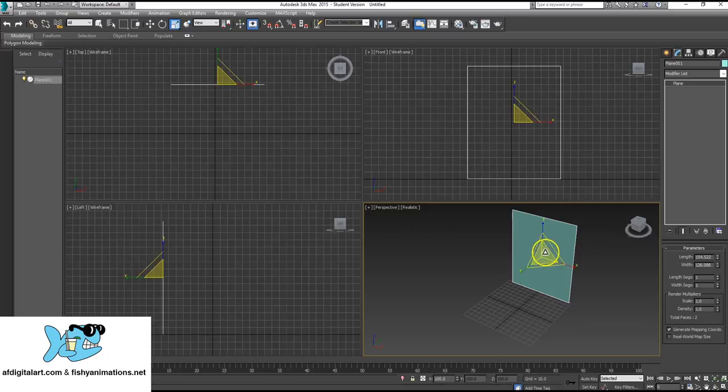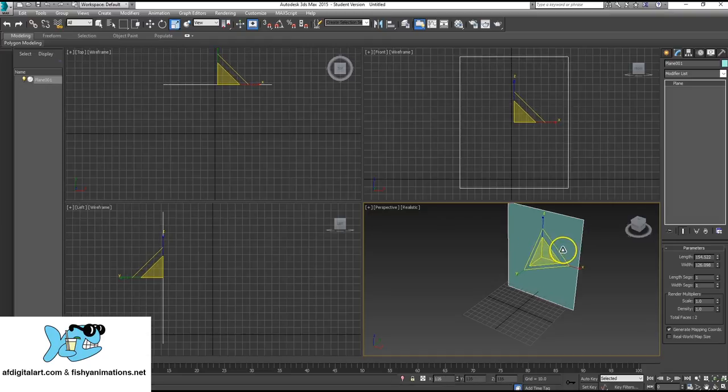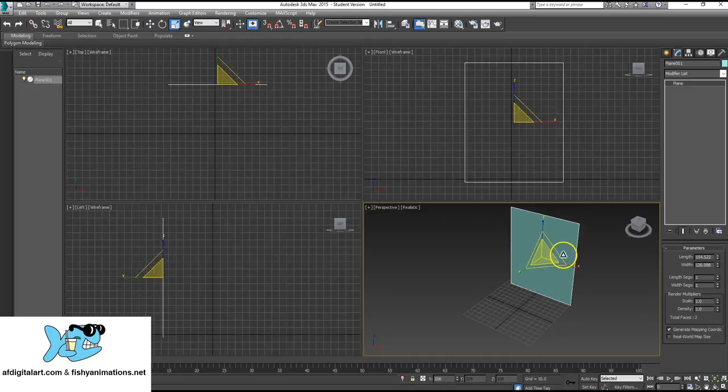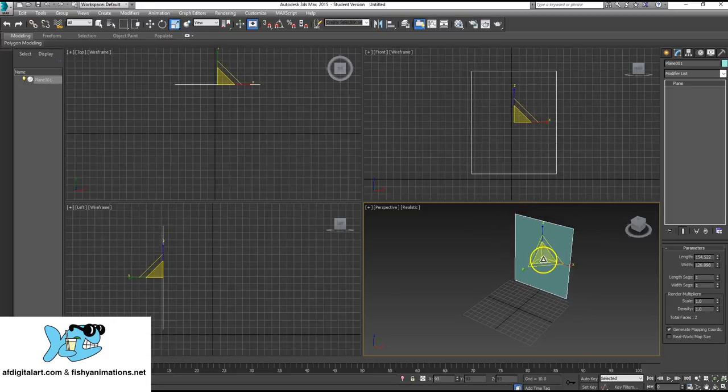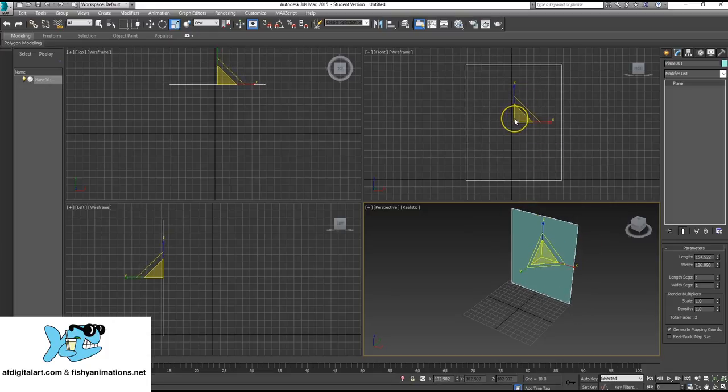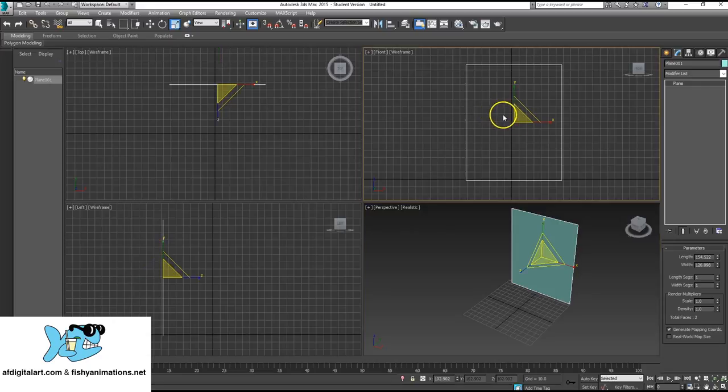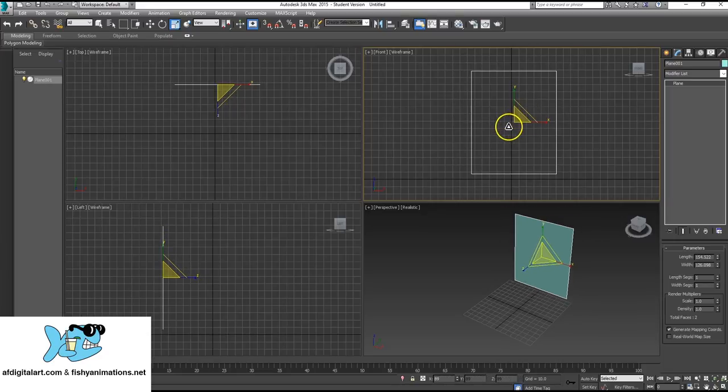So you want to make sure that you're always scaling your objects from the center of the scale tool. So if I left click and drag, notice from the center, it's allowing me to maintain uniform scale. I can do that in any view. I can use any of these tools. If I want to activate the front view, just press down the middle mouse wheel. That's the easiest method. And then notice that you want the symbol to look like this in the scale tool. So on a left click and drag, it's maintaining uniform scale.